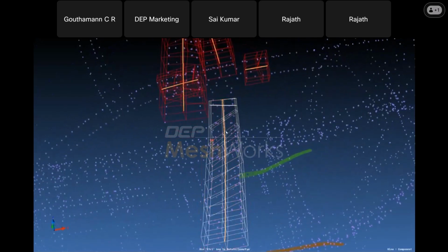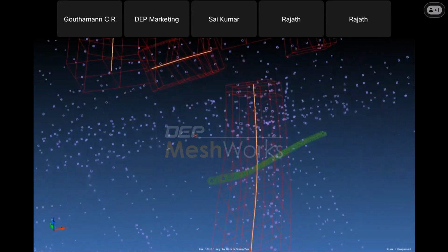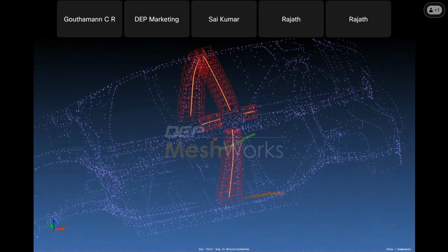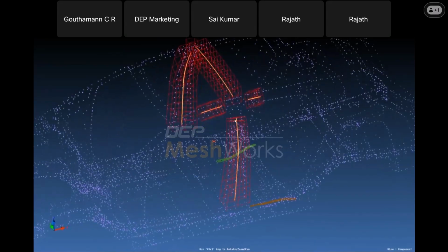So I'm going to select this block, then the CAD curve, and say pair. And I'm going to specify the number of sections here to 5. So what it will do is it will compulsorily create two sections, two 1D representations of the sections at the start point and the end point, and 5 more sections between the starting and the ending point. So it's going to create a total of 7 1D sections, which would represent this B pillar.